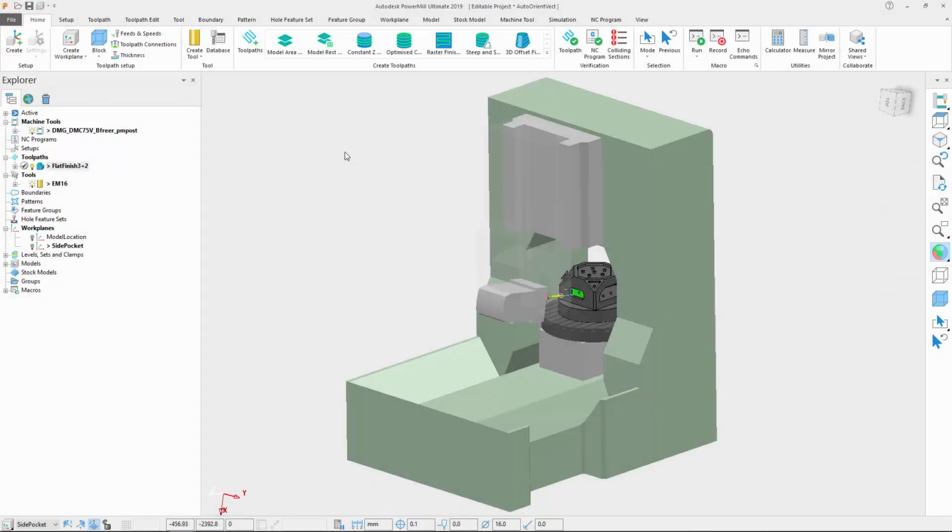Powermill 2019.2 includes an improvement to the orientation vectors functionality that reduces the likelihood of machine collisions and shortens programming time and effort. Orientation vectors were often overlooked by many users, as they required a more in-depth degree of software knowledge to be used correctly. The workflow has now been improved to add the option for Powermill to automatically save suitable orientation vectors to your toolpaths and pass that information to the post-processor for more consistent and safer results on your machine.